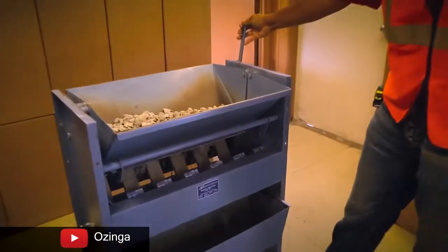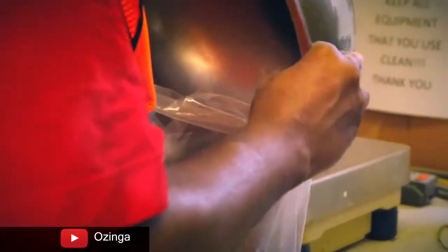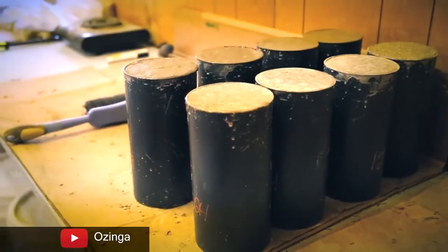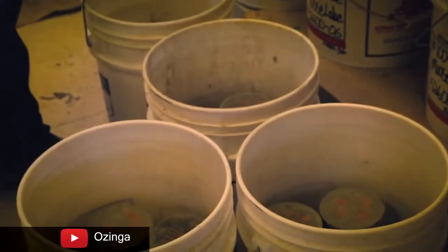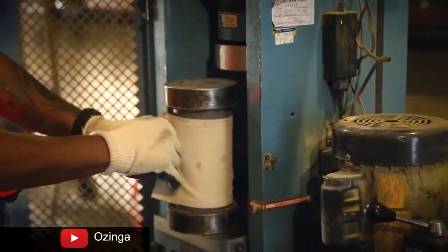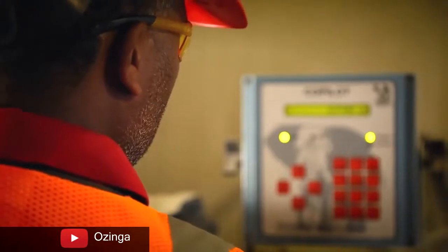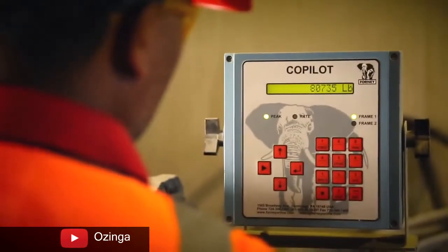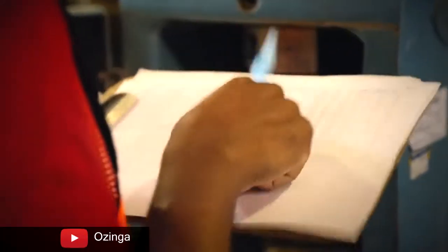We also have tests as far as in specimen cylinder tests, where we make molds based on the concrete that we tested for the day. We'll strip them the next morning and we'll cure them in tanks until it's time for them to be broken, and showing compression strength on those tests to make sure they meet those specifications required by those jobs.